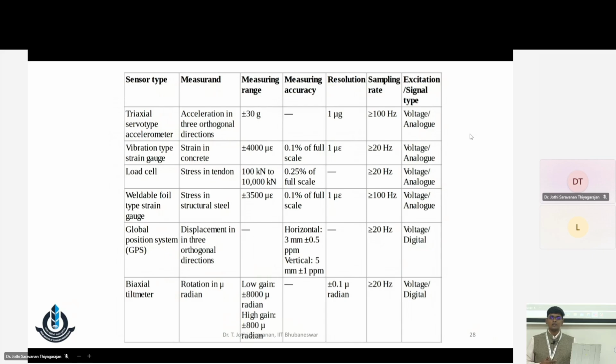Till date the government is not willing to use drone-based systems and understand this deep vision. People sitting there are not so comfortable with those things. That is fine, but they want the traditional method of contact sensors: get the acceleration data, find the frequency, plot some mode shapes, compare with Abaqus or ANSYS analysis, and they want that dynamic analysis.